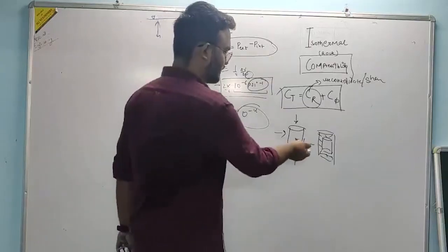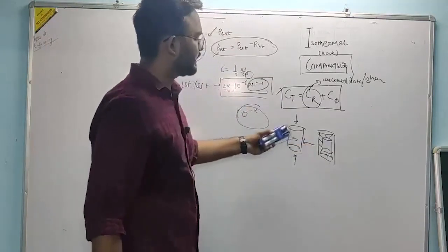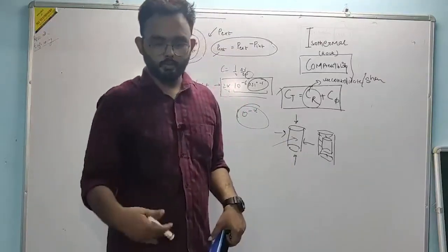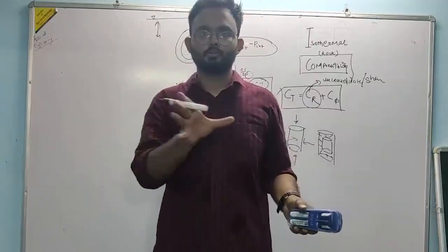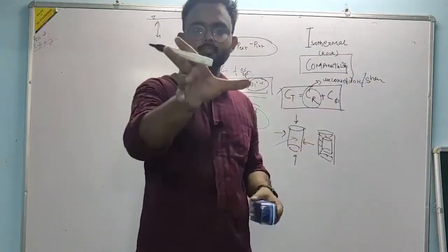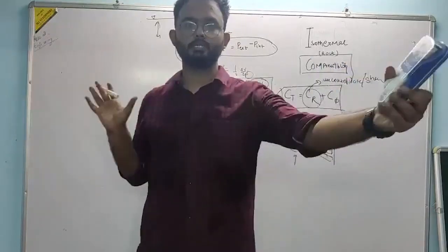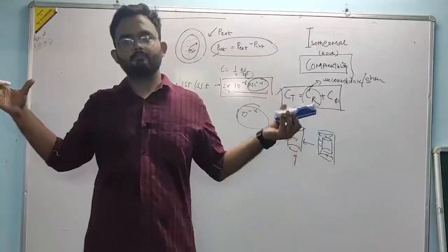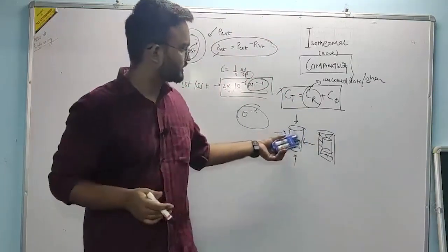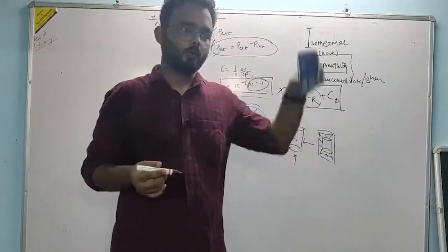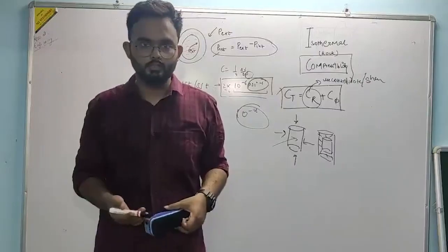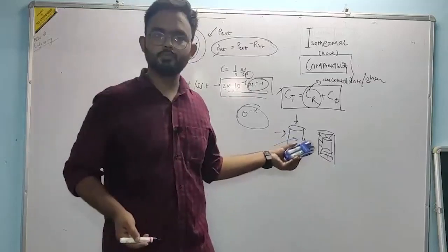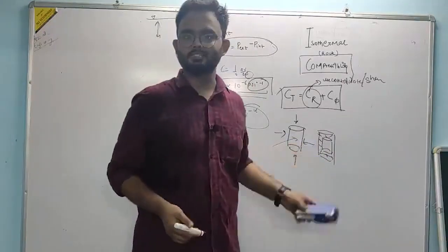In the Earth, for example, if you are building a house, you lay brick by brick, so a brick in the center is crushed by bricks on each side, right? So pressure is not just one directional; it's applied from the top, from the bottom, from all directions. That is why, to get the real picture of the formation stresses, you have to use triaxial cells, right?